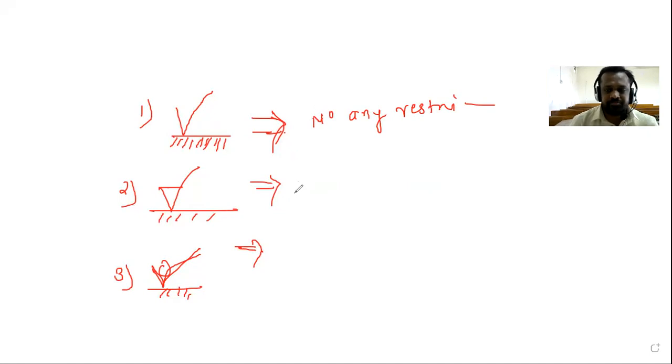If such a symbol is on your surface, what is the meaning of this? That time material should be removed. If you have to manufacture this surface and such a symbol is on that surface, you have to understand we have to produce this surface, but during the production you have to remember material should be removed.